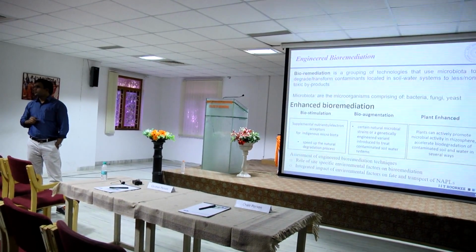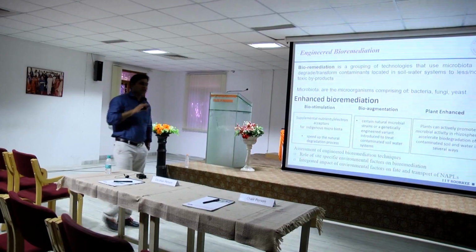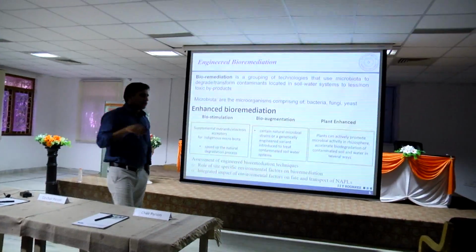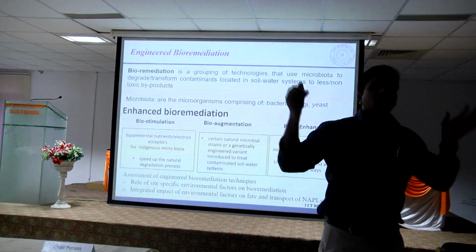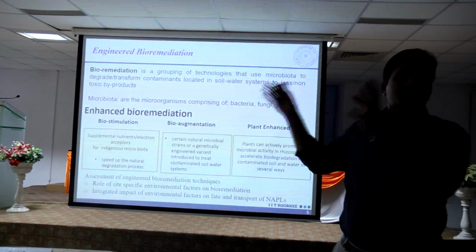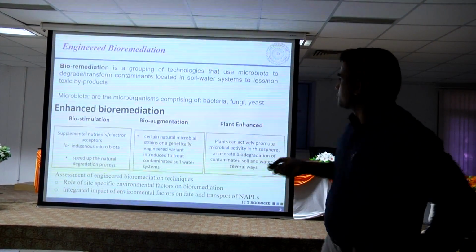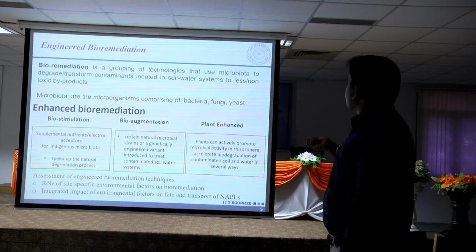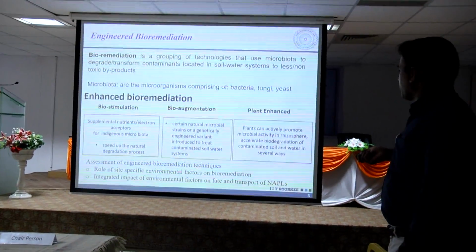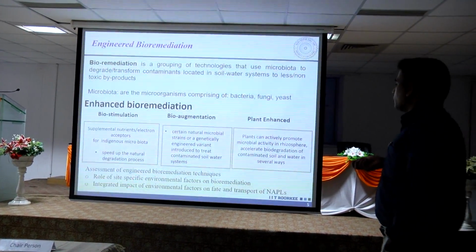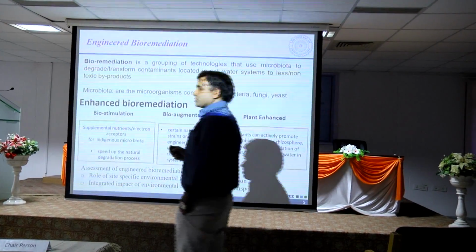So in that case, one has to see the environmental conditions or the prevailing site-specific conditions for applying either biostimulation, bioaugmentation, or an integrated technique of biostimulation and bioaugmentation. That is going to be all these together. And then the third technique, that is the plant enhanced bioremediation. So in the assessment of the engineered bioremediation techniques, the role of the site-specific environmental factors is becoming very crucial.